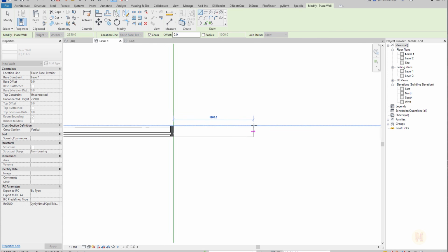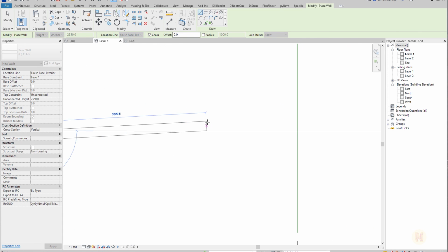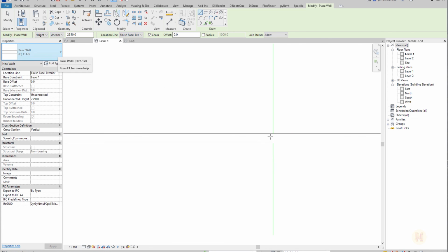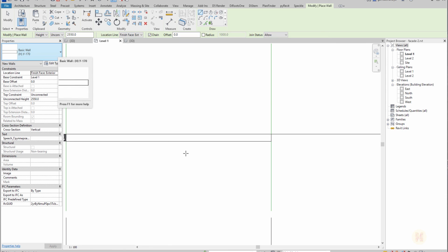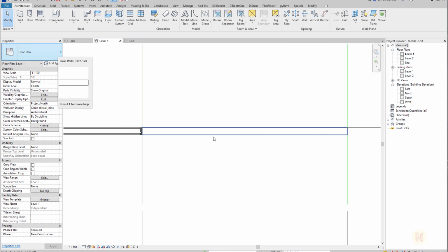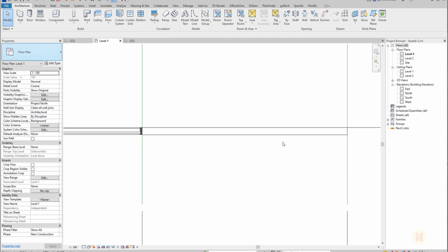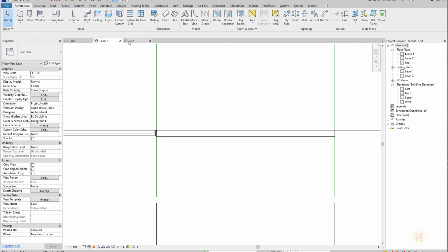Actually, this is not a wall. This is what I'm using now. Actually, this is insulation, and as you understand, insulation is part of the facade. So if it's part of the facade, it doesn't necessarily have to be placed exactly on the floor, because it's connecting to the wall, so we will create the wall later on. But now we are working with the facade. So we created our insulation.